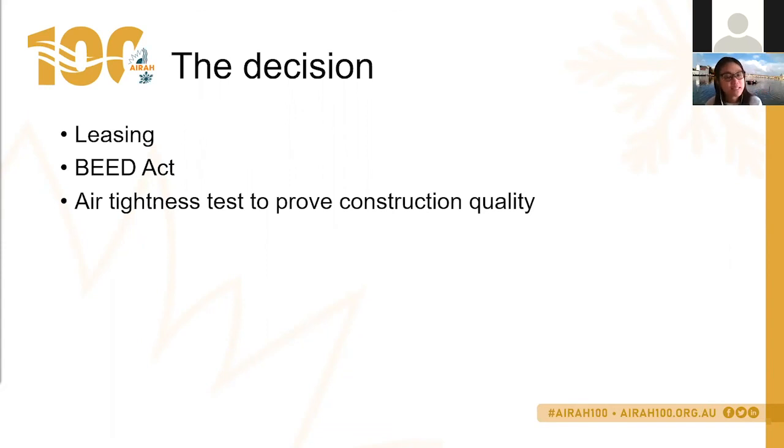If the building is subject to the BEEC Act, which covers the requirement for NABERS energy ratings to be conducted for all buildings over 1,000 square meters, then more than likely this makes it easy, because during the operational phase, these buildings already need to undertake a NABERS rating. So the question is really just around the design stage, of whether or not they want to sign a NABERS commitment agreement, but also conduct additional modeling to prove that.